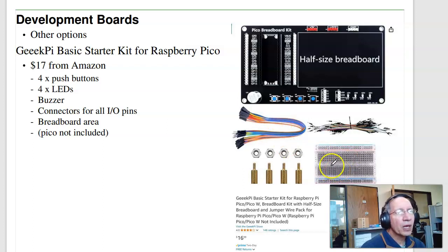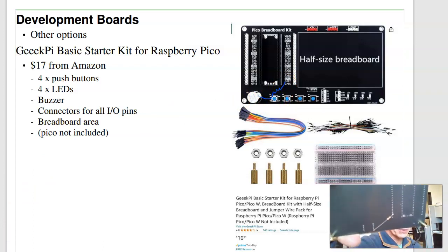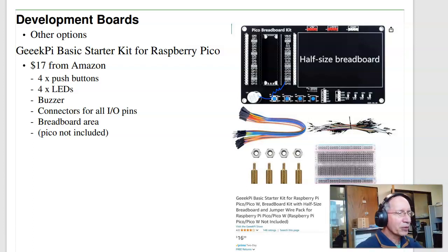Yeah, pretty nice kit. Kind of one word of caution. If you plug this guy in, the buzzer goes off. What you need to do is take a resistor from the buzzer and solder it, like a 100K resistor, to ground. That has a floating buzzer. Ground it, the buzzer quits chirping at you. And you can see that on the back of my board. There's a 100K resistor I soldered from the buzzer to ground. Keeps it from chirping when you plug it in.